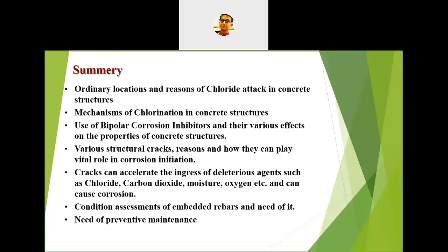As early as possible, if you see any cracks, we have to repair them to save the structure. These types of repair come under protection, not prevention. Using corrosion inhibitors comes under prevention, at the very starting stage. If at the time of construction itself you take measures to resist corrosion, this comes under the prevention methodology.